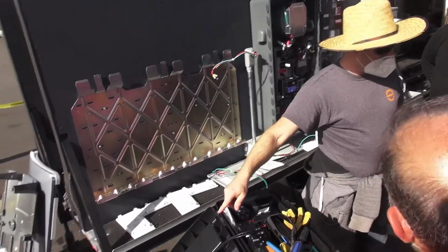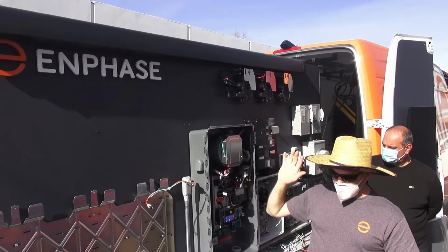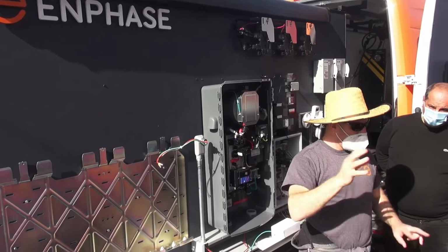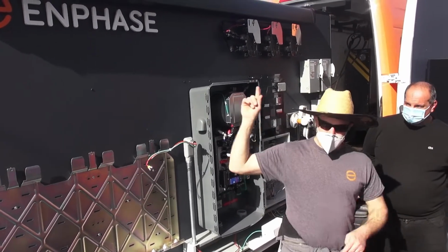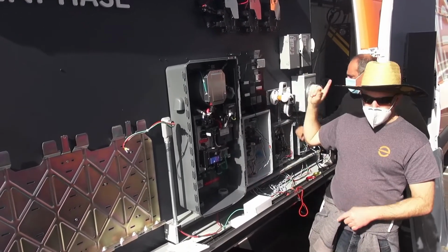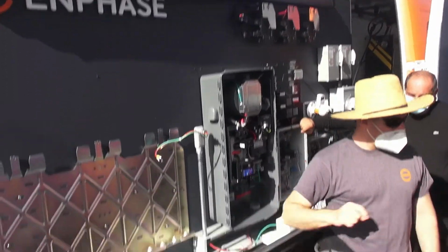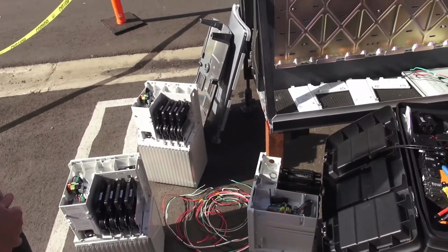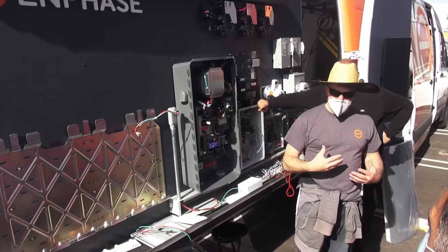These IQ8 bats and the new IQ8 PV ones, when the grid goes away, can change modes to become a grid forming mode. That's what's different about these versus the other ones. Technically with IQ8 PV, you actually can install backup without battery storage because they have that ability to do grid forming. It's new, it's just a new feature.